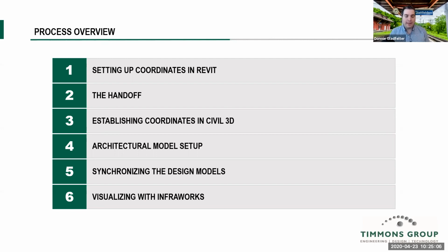And so with that, what you may need to do is actually have multiple civil models, one for each building. The good news is once all of those models are referenced in a geographic coordinate system, you can link all of them together through the survey point. So you might have to do a couple of different pass-through models. It can be done, but it gets a bit more complicated.